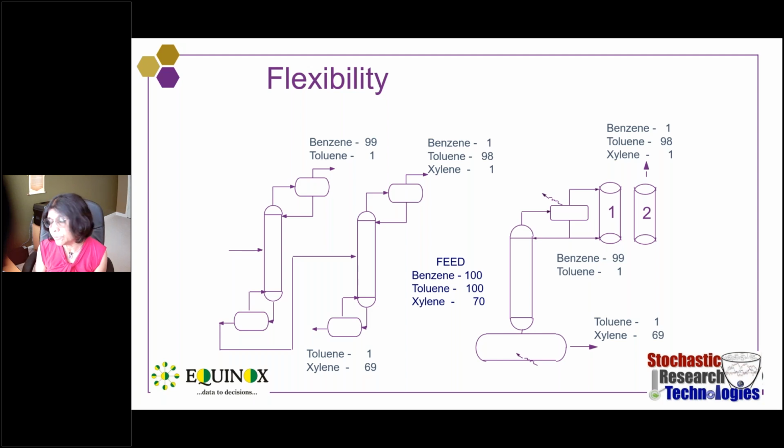So for example, here I'm showing a 3-component mixture. If you want pure components, then in continuous distillation, you have to use 2 columns, n-1 columns. While in batch distillation, you can actually get 3 products by taking different cuts from the same column, different fractions per cut. As time goes by, number 1 will be the first product, number 2 may be the second product, and whatever remains may be the third product. So you need just 1 column to separate this mixture.